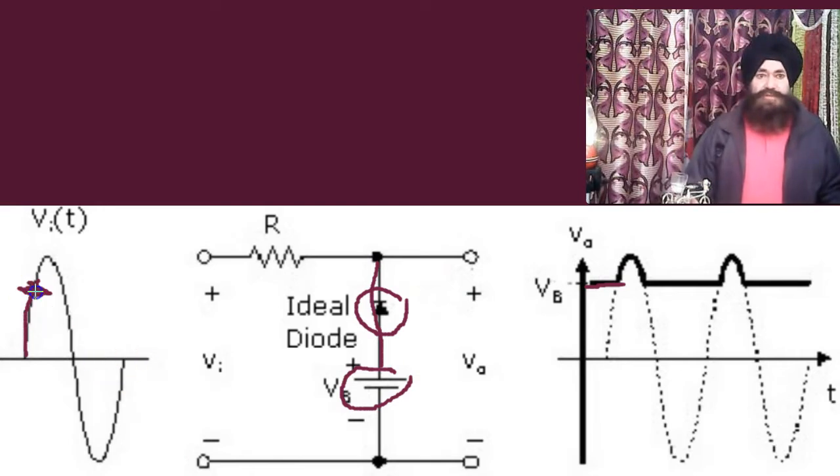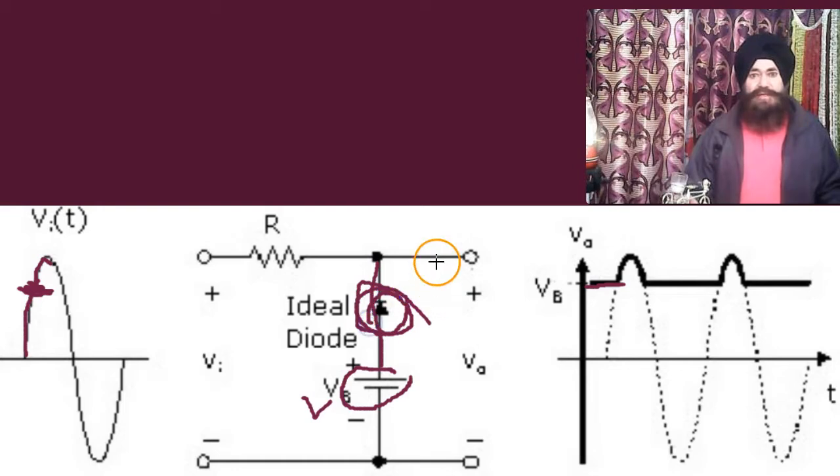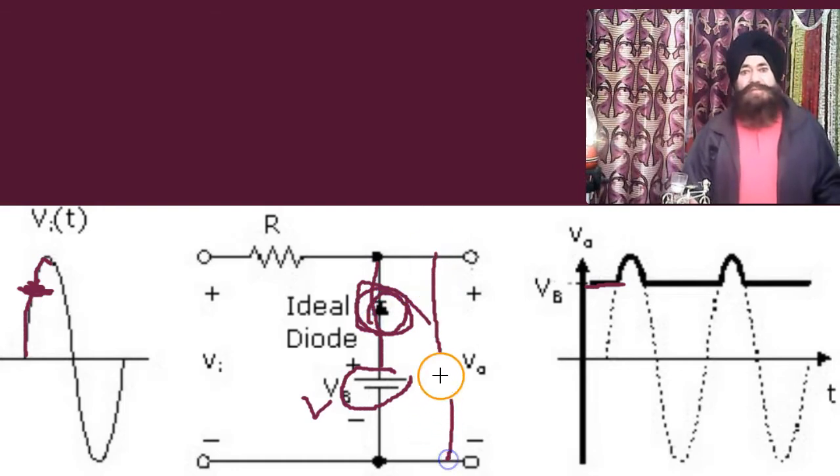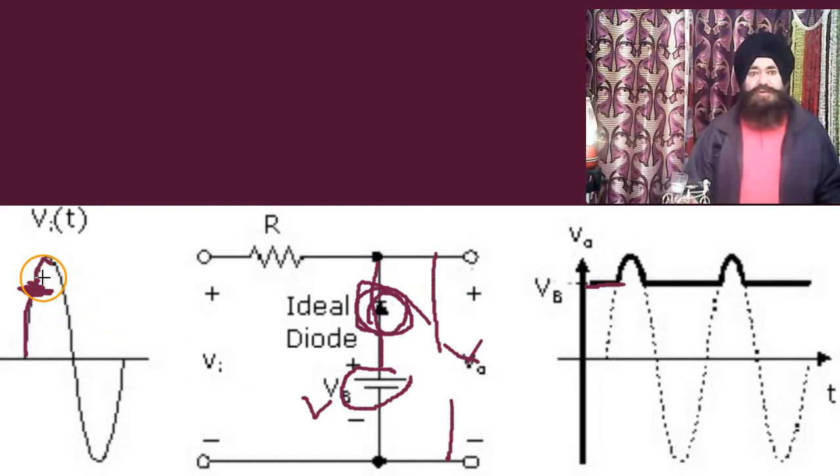And the voltage goes high from this level. So now positive is applied to N, and this voltage is going to be greater than Vp. So it makes it reverse biased. When it is reverse biased, it acts like an open circuit. If this is an open circuit, then whatever the voltage changes here, the same voltage appears at this end, because current cannot flow now. So this voltage is appearing.